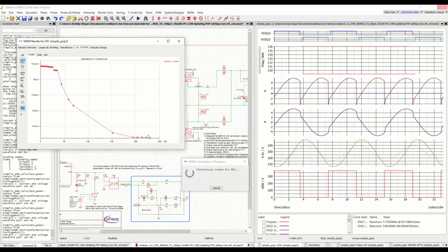And we calculate the plot up to the maximum flux density. For example, for this inductor, you're not ever going to operate it near 200 amps or 150 amps, but if you just take that geometry and see what current you're getting at Bmax, that's what you're getting.